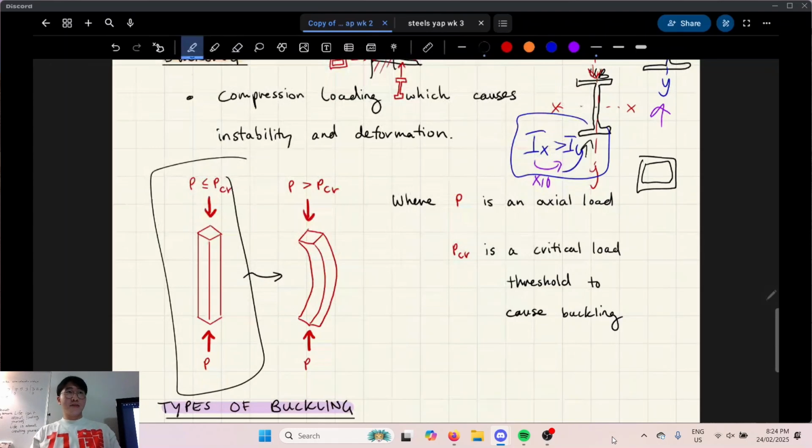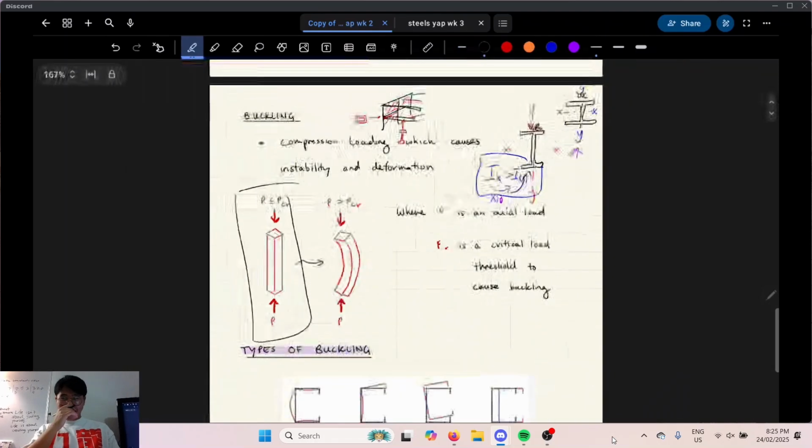What about a circular hollow section? That works as well, but circular hollow sections are not really used, because they're hard to connect things to. What about a triangular one? It's strong, but it can only be bolted like that. What if it's a square with a circular hollow section inside? I've never seen that in my whole life. Okay, but yeah, makes sense.